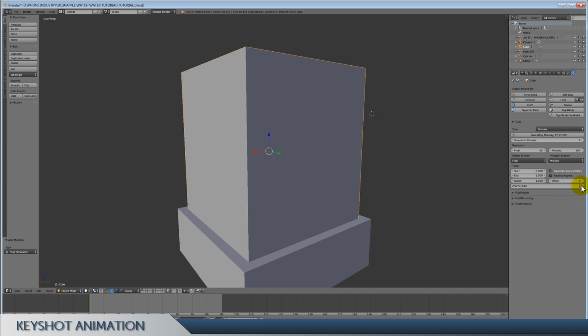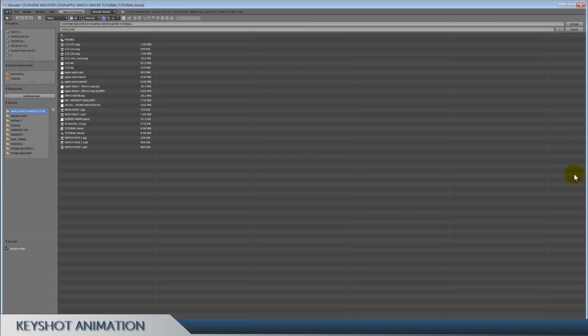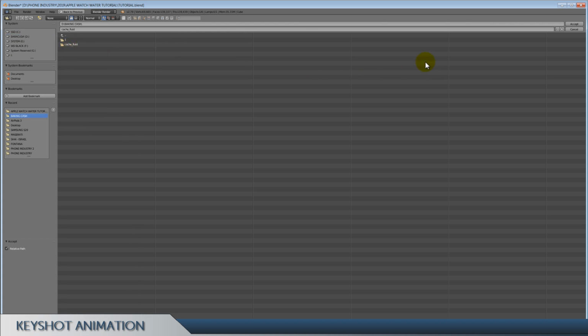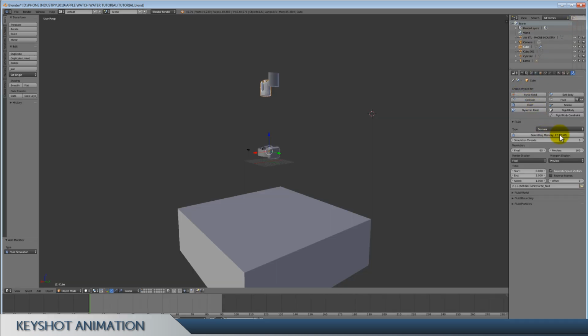Yeah, you have to enable here. So find a folder where you can put the caching file. The caching file is gonna require a lot of space. So find a disk drive in your PC where you have a lot of space, and depending on your desires, it may really need a lot of space for this one. At the moment it says like 17 megabytes, but trust me, you're gonna go above 2 gigabytes easily.